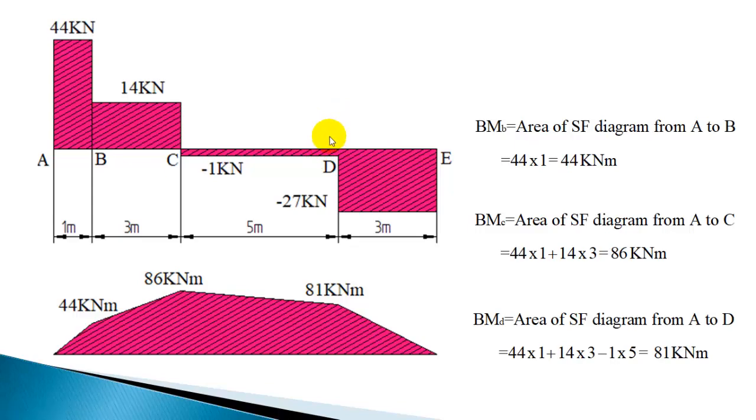So to calculate the bending moment at any section, you calculate the area of the shear force diagram from the left hand up to that section. Let us work out another example.